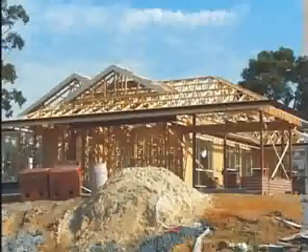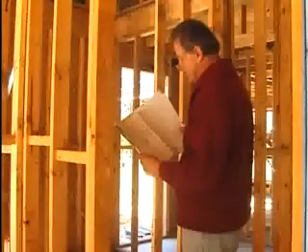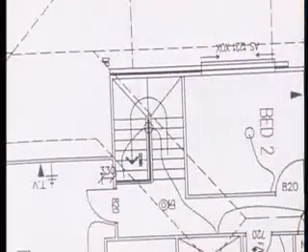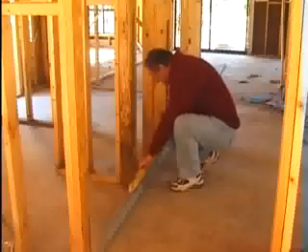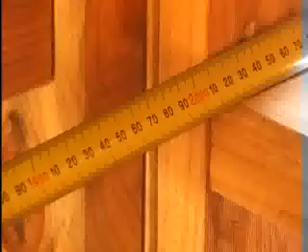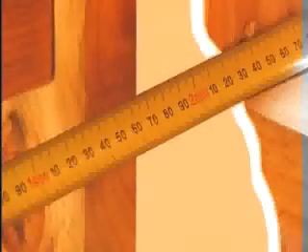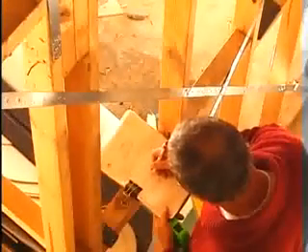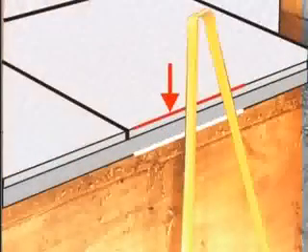On a new construction site, measuring for stairs is usually more straightforward. The position for stairs will have been allocated in the design. However, the usual checks for level floors and plumb walls still need to be made. Measurements between walls must allow for the thickness of wall linings. Height measurements are floor to floor, but checks should be made for variation in floor covering thicknesses.